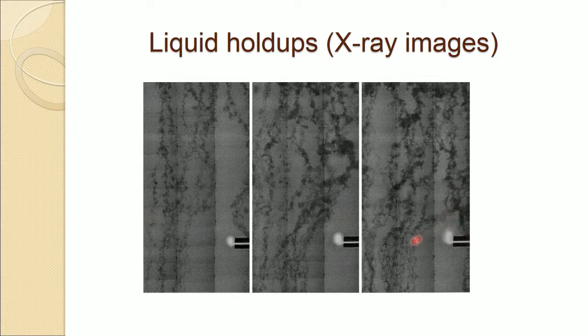So, one would be seeing a big deviation of liquid away from the raceway, but in an actual situation density is almost 7 times more. One would not expect that much deviation here. One can expect some deviation, but not that much, and certainly liquid would be going more at the back and coming down this way in the raceway region.